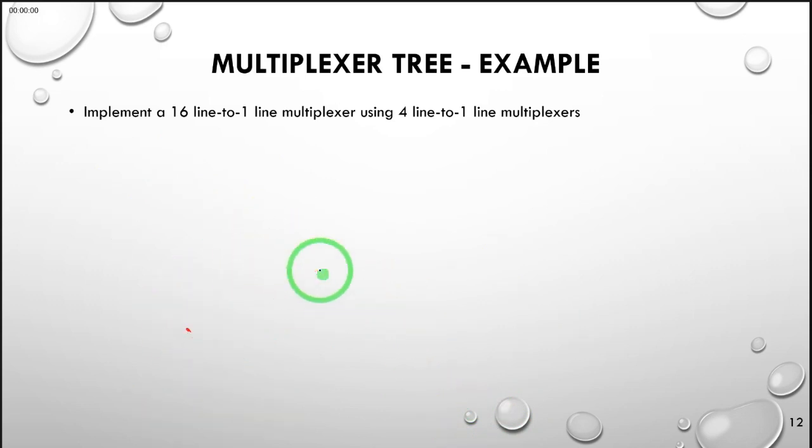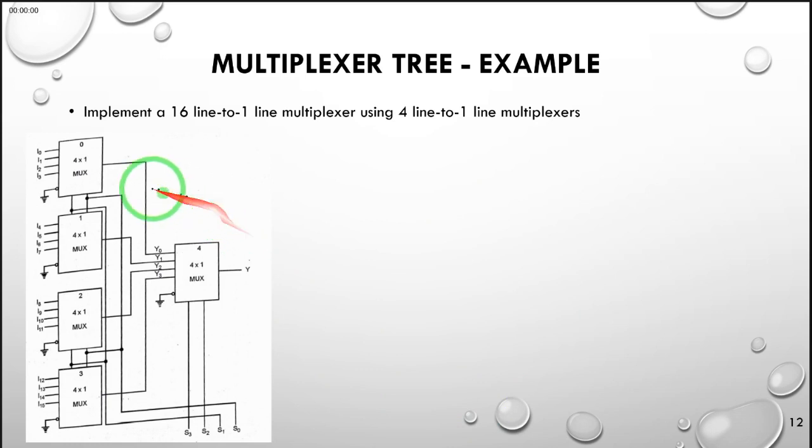So if we now look at this diagram, what we see is the same design, probably in a better organized format. The uppermost 4 significant bits are represented by multiplexer 4, and the second 4 most significant bits are inputs to multiplexer 3. The least significant 4 bits are the inputs to multiplexer 1, and the second lowest significant bits are inputs to multiplexer 2.